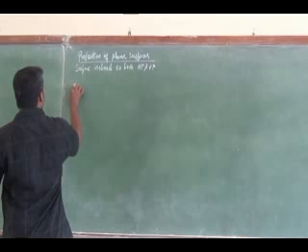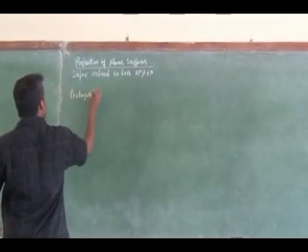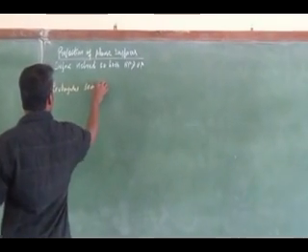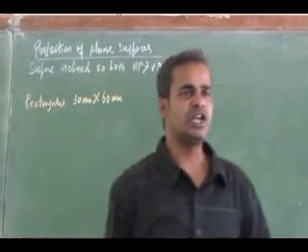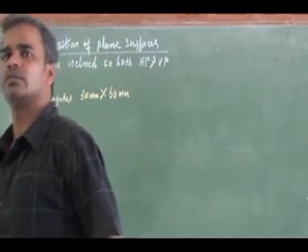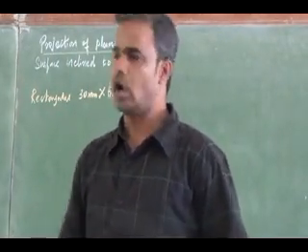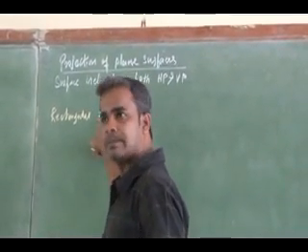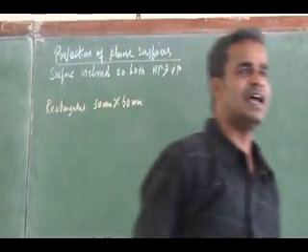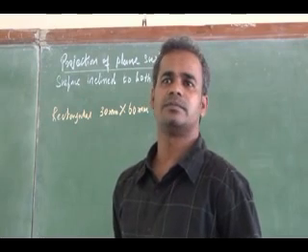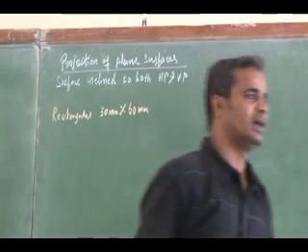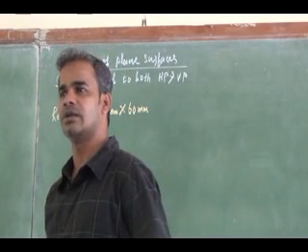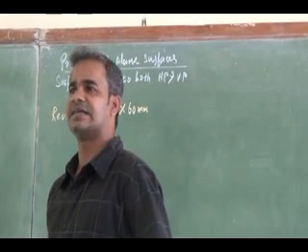Okay, the next variety of rectangular lamina of size 30 mm by 60 mm is resting on the ground. Resting on the ground in the sense what? Ground means horizontal, resting on the ground with one of its shorter edges, shorter edge in the sense 30 mm, such that the surface is tilted to give the final top view as a square.